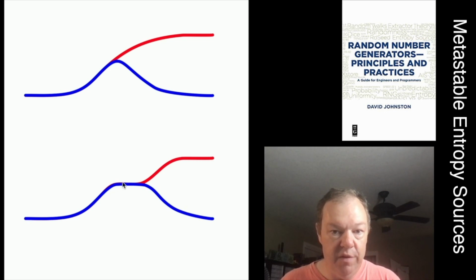And the length of time it persists in this metastable state is an exponentially decreasing function, right? So the probability of it diverging early here, so the circuit is powered on, both ramp up together as the voltage is increasing, and then some noise causes them to start diverging. So this ramp here is actually the power on ramp of the circuit, and at some point it starts diverging. But it might stick in the metastable state for a period of time, and the chances of it not having diverged by some time exponentially decreases with time. So this bit here, where it's hanging around in the middle for some extended period, is much less likely than this happening here.